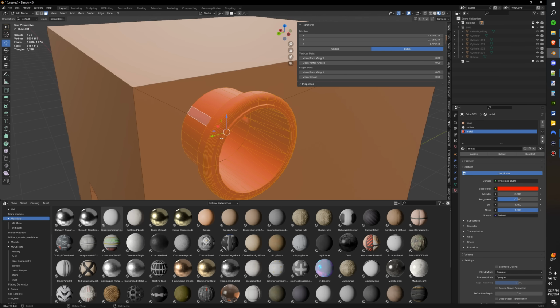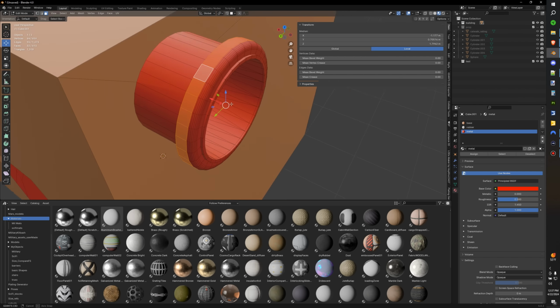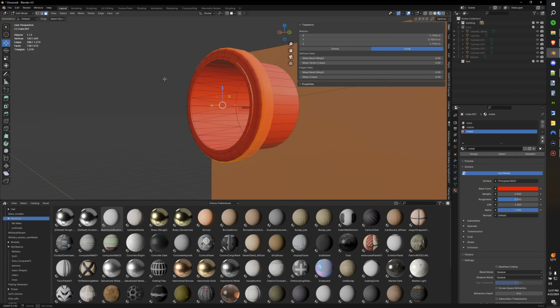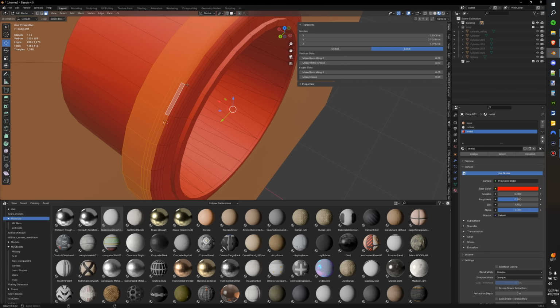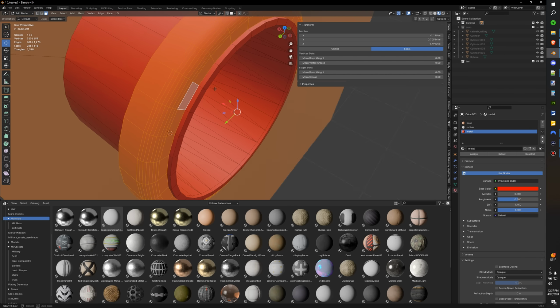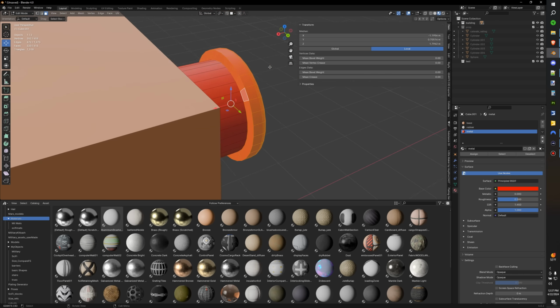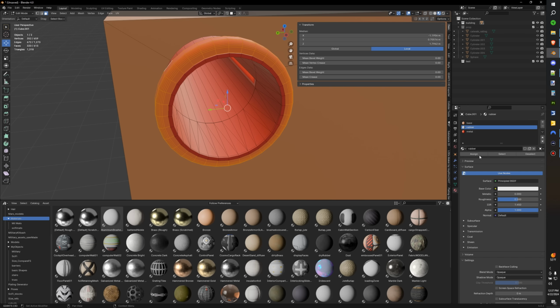And then for the remainder of this, I want to select the lips here. We're going to scroll right down in here, and holding Alt and Shift, select right on the line, and it'll select that whole ring. Right? And then you can slowly click on each one. There are some shortcut codes to do this faster. I just can't remember them. We're going to make that whole lip right there rubber. So we'll click on here, click assign, and now that's rubber.